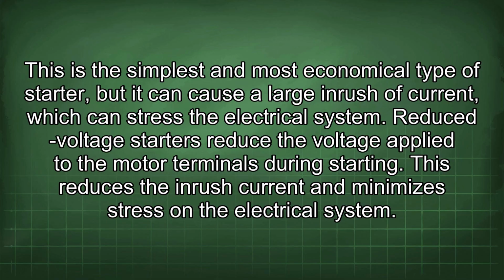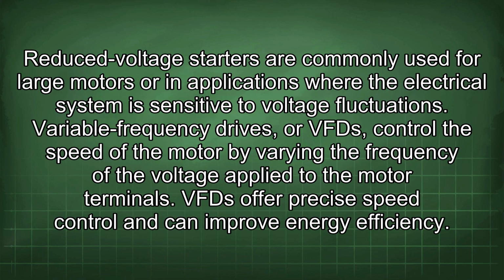Reduced voltage starters reduce the voltage applied to the motor terminals during starting. This reduces the inrush current and minimizes stress on the electrical system. Reduced voltage starters are commonly used for large motors or in applications where the electrical system is sensitive to voltage fluctuations.